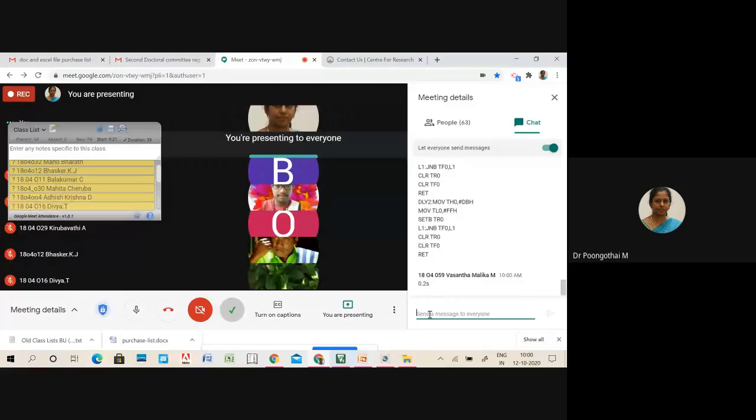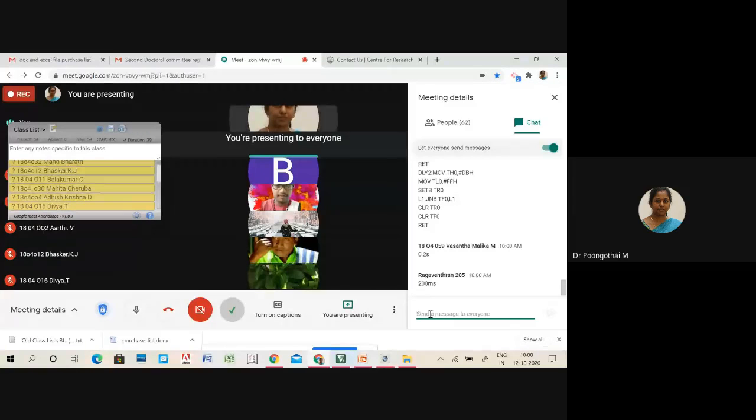So in 200 millisecond, we have to calculate the value for 25% duty cycle on time. What is the 25% value of 200? 50. So 50 millisecond will be your on time period, and 150 millisecond will be your off time period.